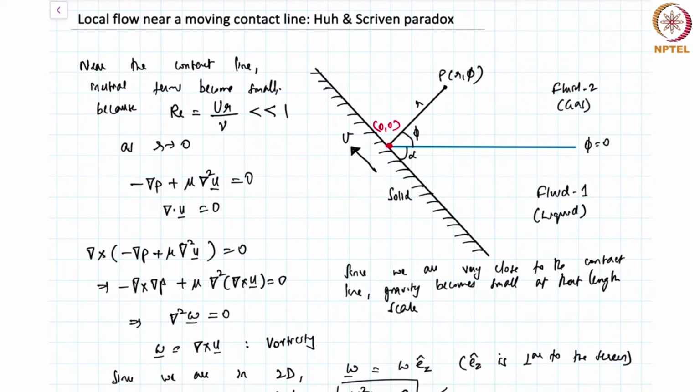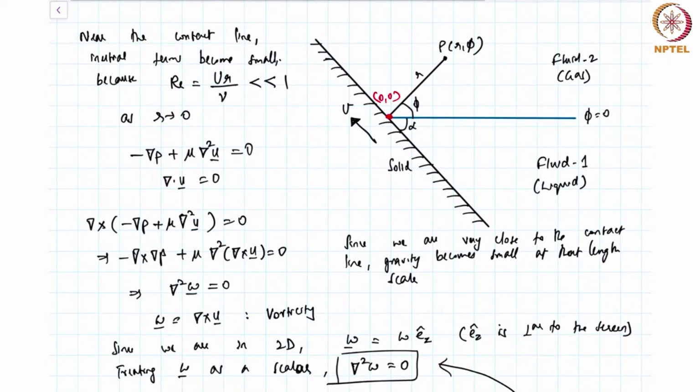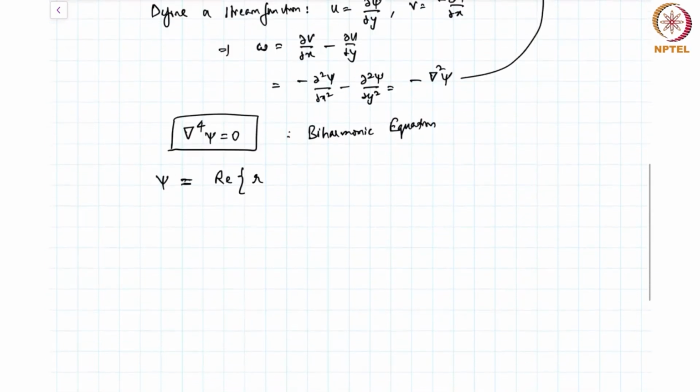So the most common gas is of course air itself, and primarily the viscosity of the gas, if you recognize, is very, very small compared to the viscosity of liquid, typically about 50 times less than the viscosity of most liquids. Like you would say the viscosity of water is 50 times more than air. You can actually ignore the effect of gas, but we'll come to that later.